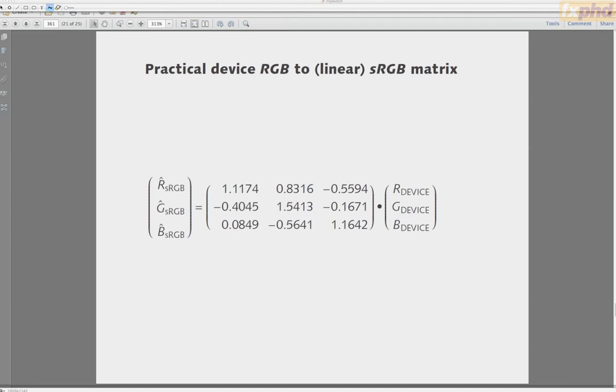So the basic idea is that these emerging displays with RGB LED backlights have got native wide gamut capability, but different native RGB spaces, but they all have, or most of them have, signal processing circuitry built in to do the transforms down to a narrower space. Well, P3 will be typically a little tiny bit narrower than native space. Rec. 709 is quite a bit narrower than the native space. And it's just 3x3 matrices in the signal path that are doing that for you.